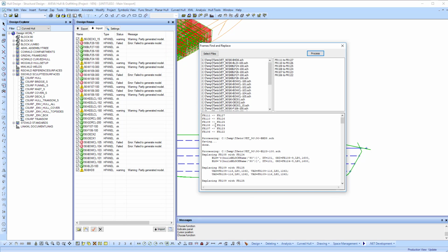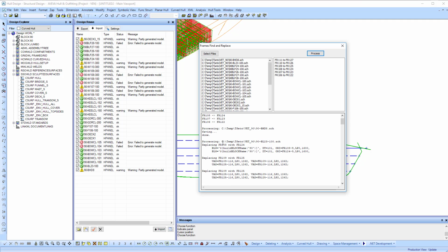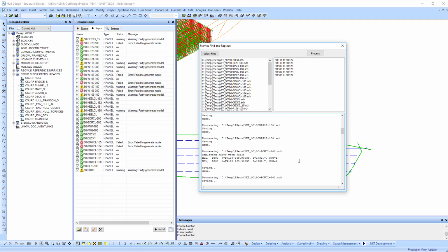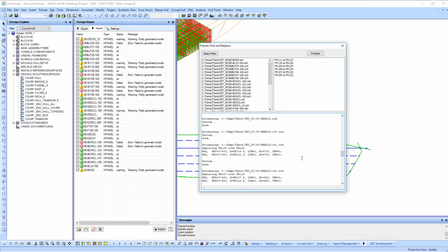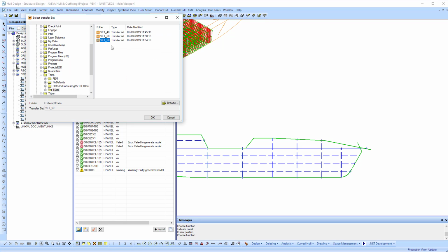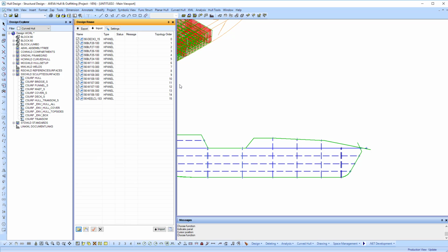So in this case, I wrote a very quick application that would just go through these files, say for example changing here 108 to 124, and typically with all the other occurrences that I need to. So there's about 15 changes across the entire data set, just the frame references, no coordinate transformations. So now we'll bring that data back in again and import it.